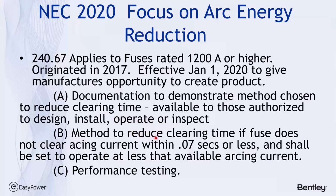The method to reduce the clearing time, if fuses do not clear the arcing current within 70 milliseconds or less, shall be set to operate at less than that available arcing current, and it needs to have performance testing.